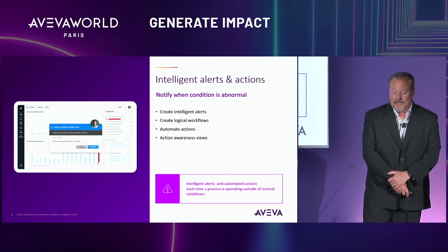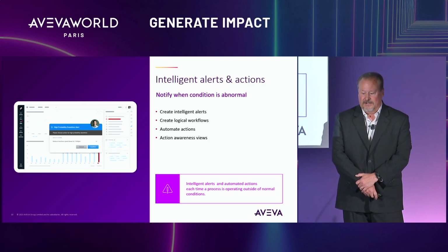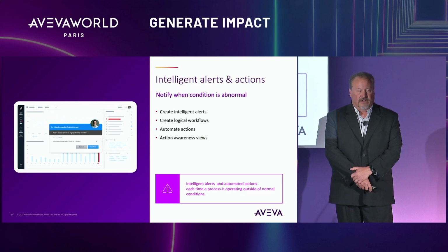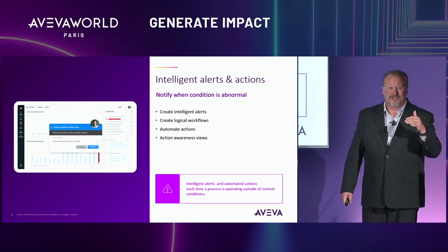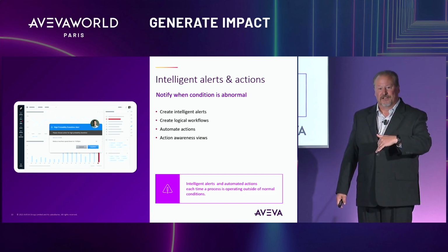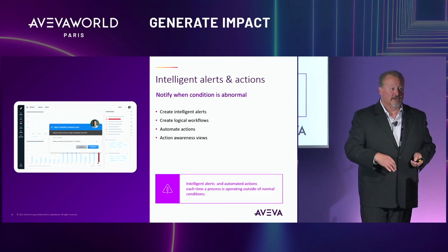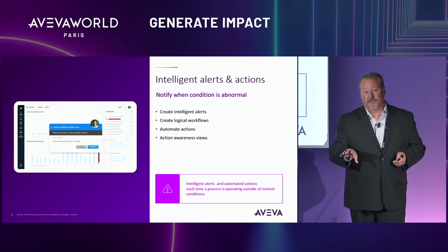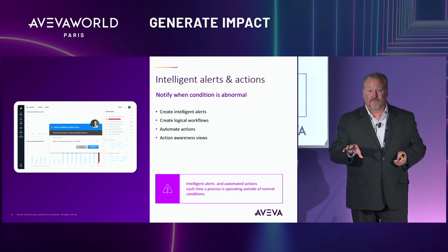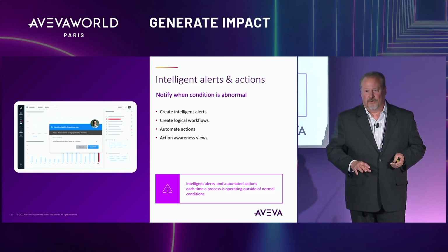The other really interesting thing on closing the loop that I mentioned earlier is that advanced analytics will also take actions and anomaly scores and write those values back into Connect. So they can be driven all the way back down into your control system, whether it's back to the operator display or even all the way to a PLC for set point analysis or taking action on the plant floor. So this is the closing the loop that Rob talked about in the keynote.